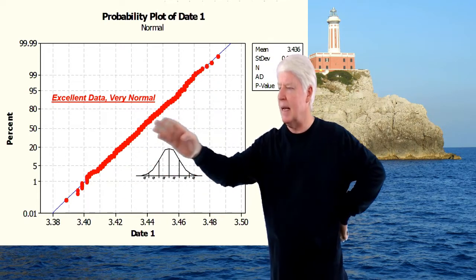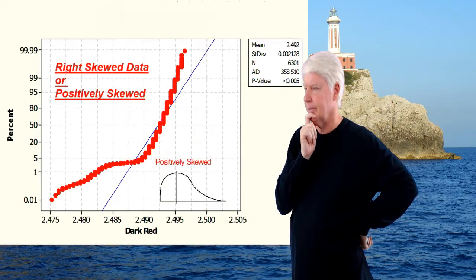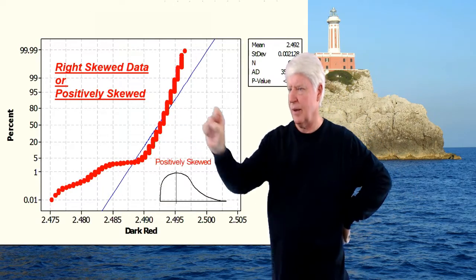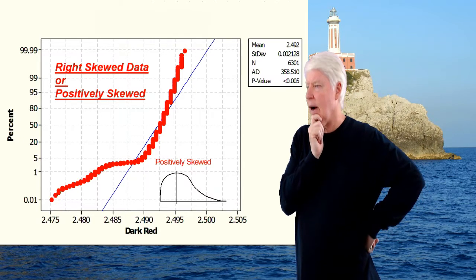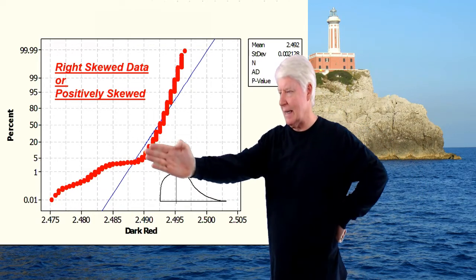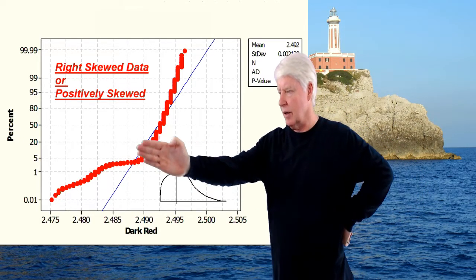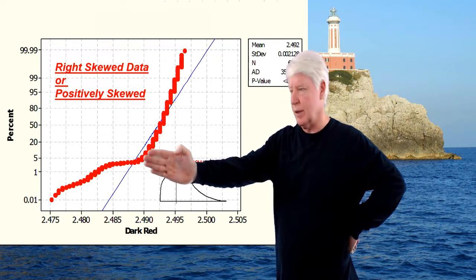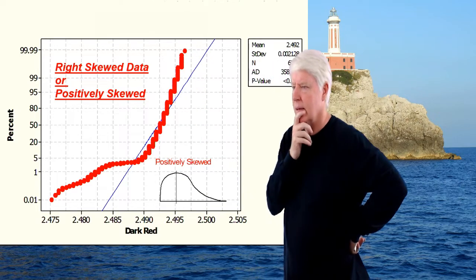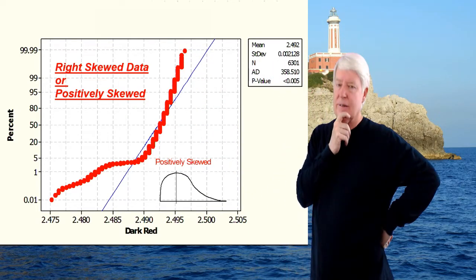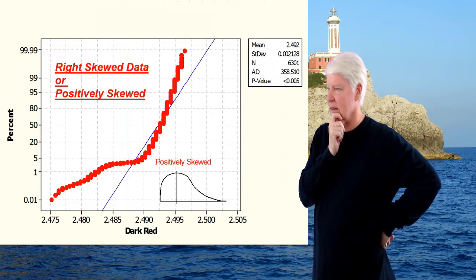That means you have plenty of measurement resolution there. This one, they're stacked. So there's some resolution issues on this, among other things. Now, if you dug deeper, you may find that, again, I got data from two different part numbers. This part number and this part number. So there's many things you can investigate when things aren't normally distributed.